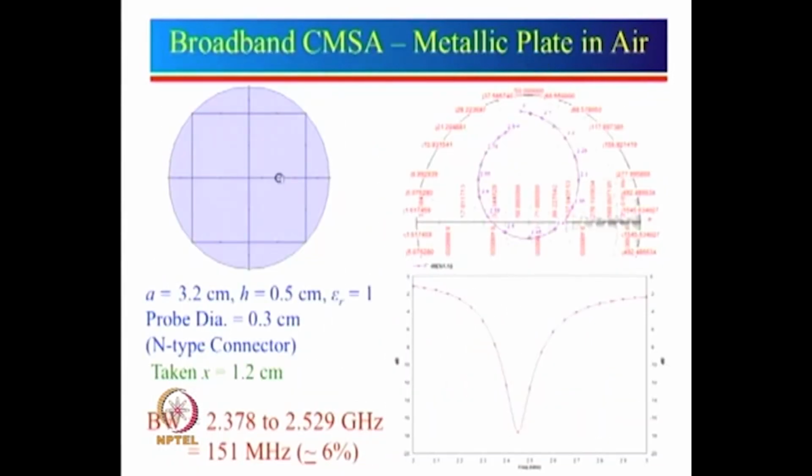So in fact, if you add a little bit of thickness here, what will happen is that effective a will increase, which will reduce this resonance frequency. As I mentioned, I had taken a larger margin on the higher side, so that will do the job. So if you use this particular dimension with a proper support, it will easily cover the Wi-Fi.